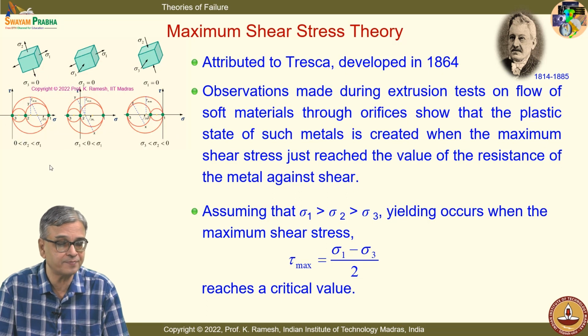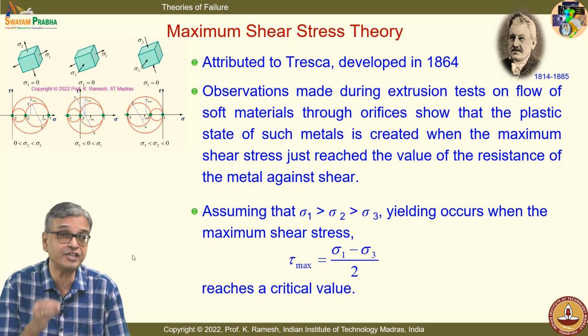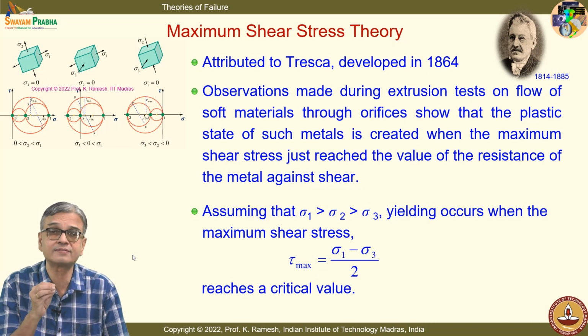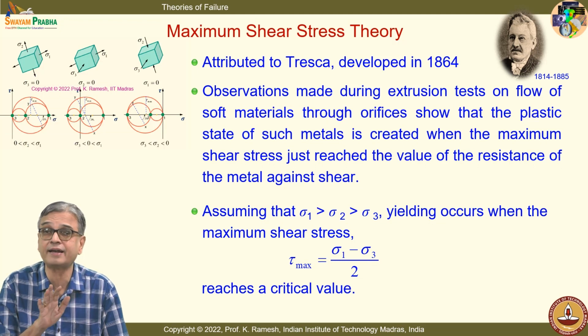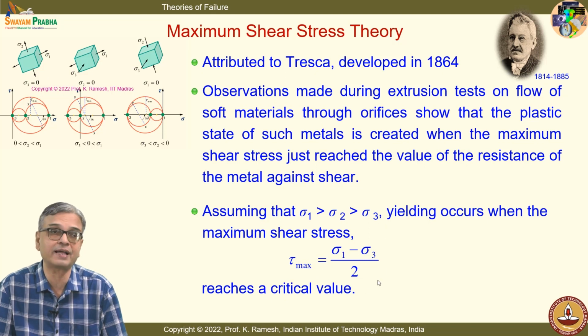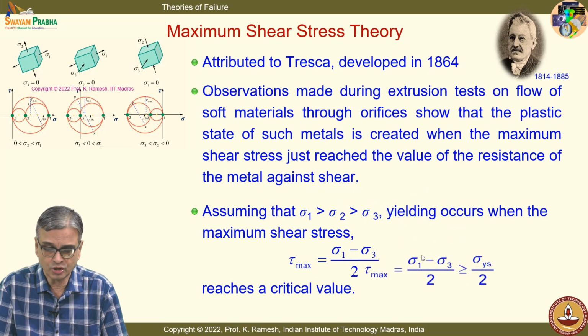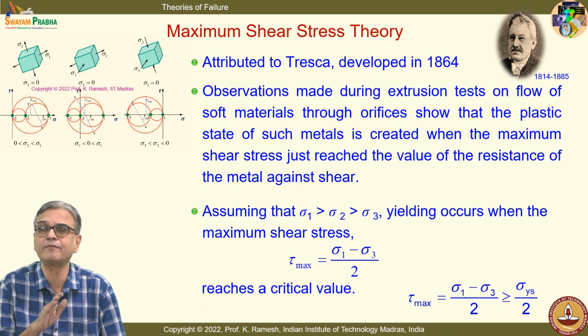What is shown here, as we have discussed, is that I could have both the principal stresses positive in a two-dimensional scenario, and both the principal stresses negative in a two-dimensional scenario, the third principal stress being 0 plays a nuisance value. I have cautioned, even your simple thin cylinder, the Coke can, experiences a biaxial state of stress where both the principal stresses are positive. So, you should not simply use sigma 1 minus sigma 2 and say that this is tau max, whereas it is sigma 1 minus sigma 3 that gives tau max. You can make a drastic error in your calculation if you do not arrange the principal stresses in this fashion and interpret it in this manner. Do not have it as sigma 1 minus sigma 2. You can also say sigma max minus sigma minimum, but it is always better that you write it in this fashion, (sigma 1 minus sigma 3) by 2, you will never make a mistake.